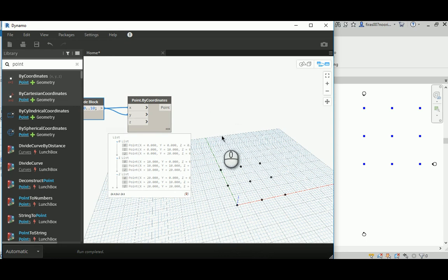Here in the direct Dynamo environment, you can test and design and fix, but when you send it to the custom node, it's really harder to control each value and really hard to test during the design process. So it's really important to keep that in mind, to design and test within the Dynamo environment before you go to the custom node.